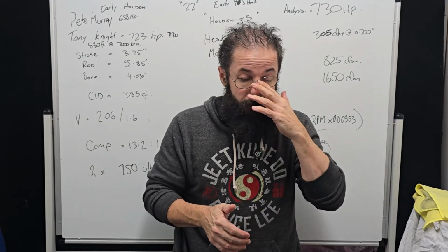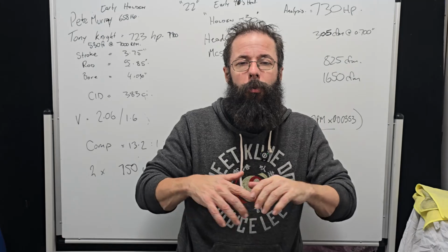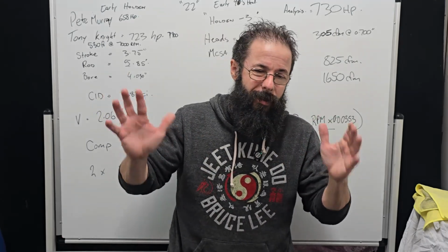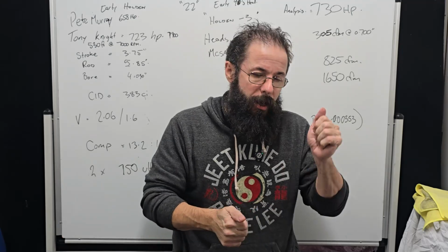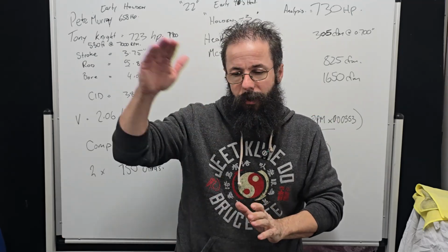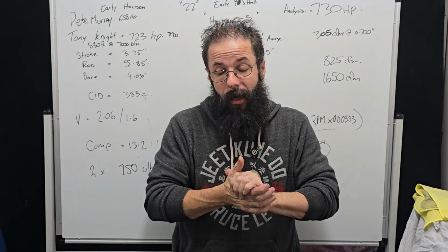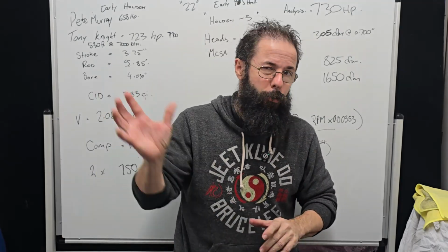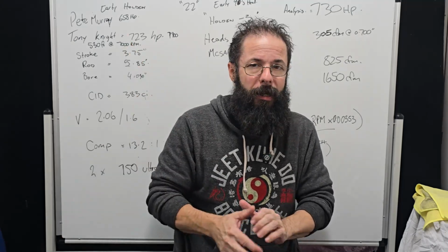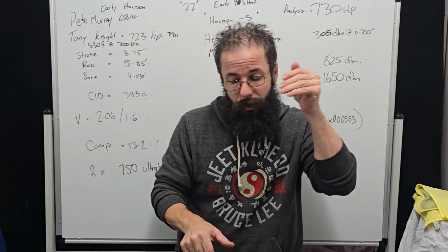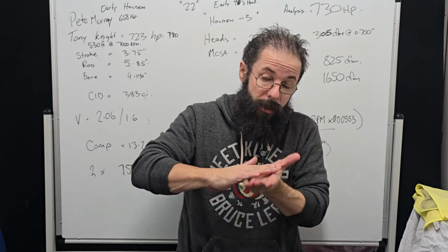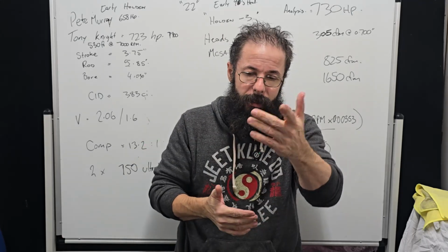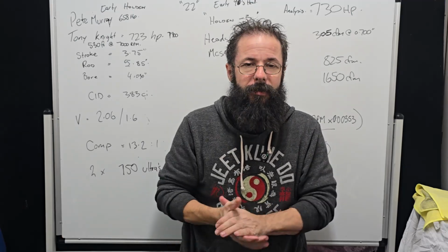Generally, a lot of the earlier Holden ones we used to do, we'd build them around the street. So they're only 550, 600 horsepower street engines, and they were just stump pullers. They're absolutely massive foot-pounds. Foot-pounds that you wouldn't even see with a dual plane, not unless you went super, super small camshaft and they had no RPM at all. And that comes down to the line of sight. The better line of sight, the higher velocity index we can carry, the more torque we can carry. And that leads us into our next thing with bends and stuff like that.